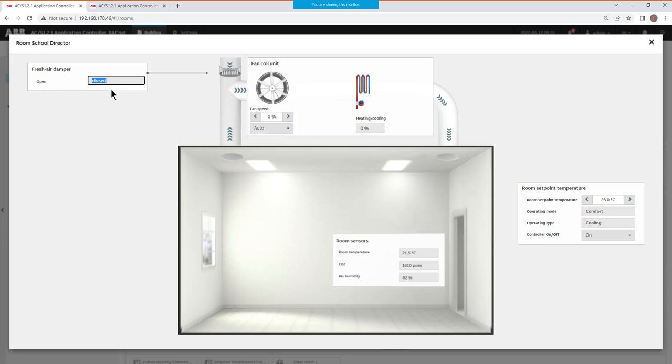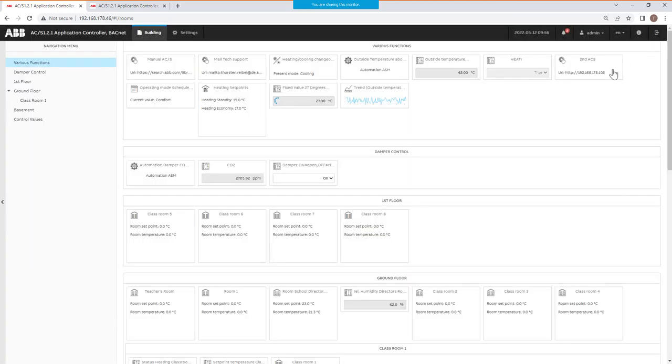I do it again. I go to a higher level, 2700, valve will be opened. So a real representation here of the function. I cannot operate this from here, but I can do it from a separate ASM I have created. Means I've programmed here an additional function to operate the damper from the web user interface as well. So on is open. Now I go to off.